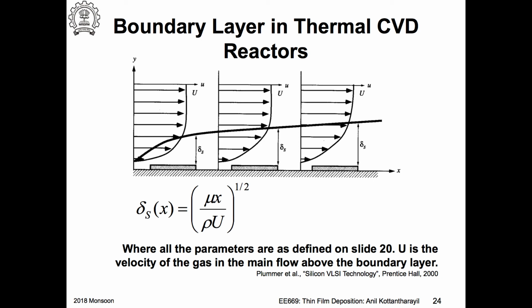So this boundary layer consideration actually becomes very important in CVD, for reasons that I've already mentioned in a previous lecture. In an oxidation process, there are two fluxes that we were concerned about: the oxidant flux through the boundary layer, and the other through the already grown oxide, and then you have a reaction flux.